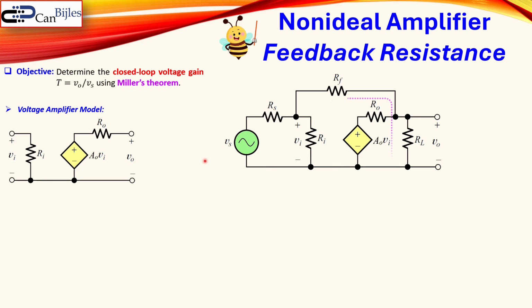Here you see the voltage amplifier model, given in this pink box. You see here the RI, RO and the voltage controlled voltage source having a value A0 times the VI. The parameters are shown here: the input resistance, output resistance and the open circuit voltage gain. What is an open circuit voltage gain? Well, it is the gain for the condition where you have the output nodes of your voltage amplifier model